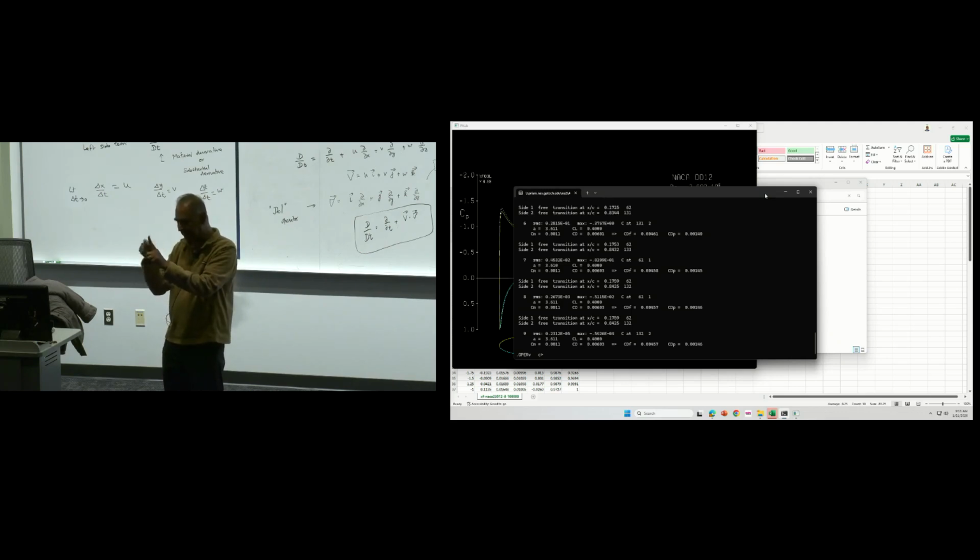It takes a while to converge, especially when you have a large region of separation. The other way people do it is to physically add that displacement thickness, come up with a new airfoil, and then analyze it. I think XFOIL uses the velocity at the edge of the boundary layer to push the flow away from the body. But depending on the severity of the problem, more iterations will be needed for this viscous-inviscid interaction to converge.